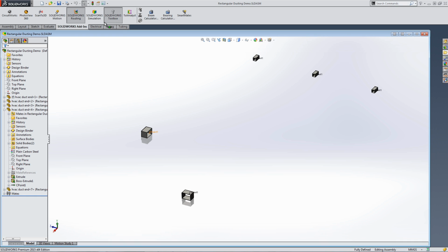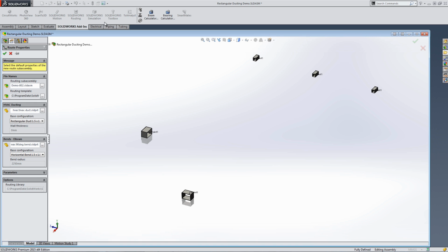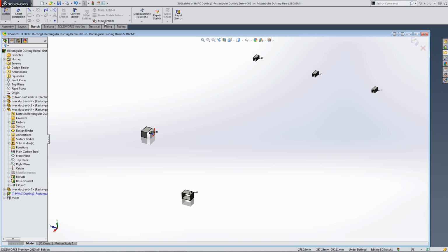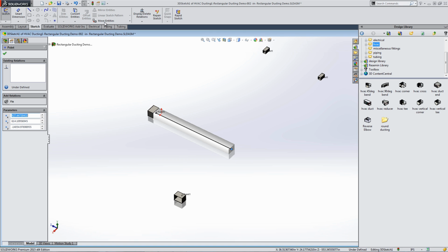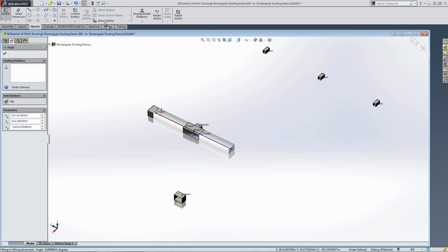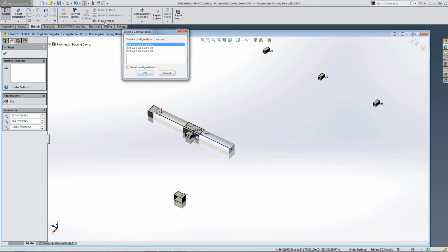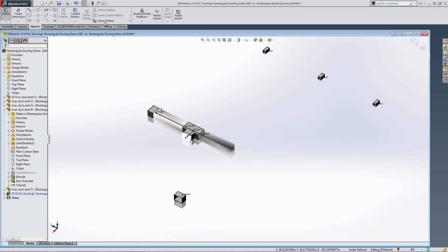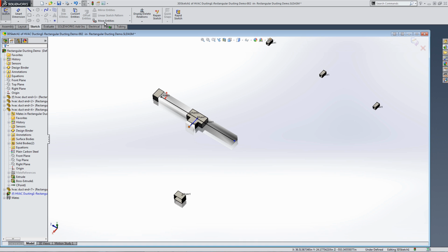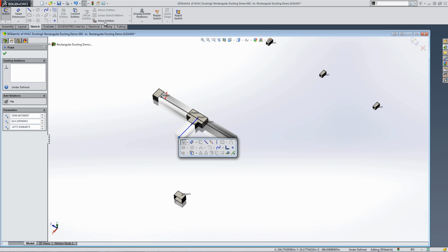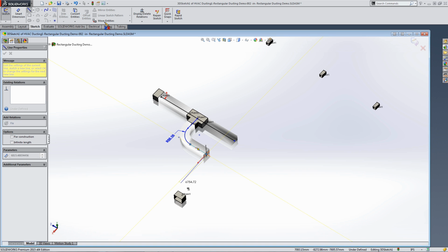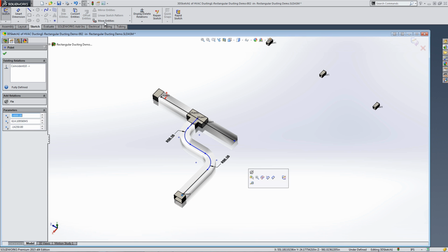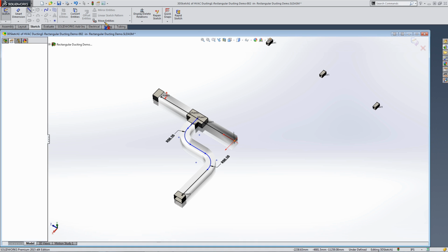So what I can do is start a route here, and what we're really looking at is a rectangular profile for HVAC. So now we support rectangular profiled parts too. So I could drag this part out and put a T on it, drop that on here, give it the same size, and let's pull this down a little bit. Maybe we have to jog around a column or something like that, so we're going to make an S-curve over here. Snap this right onto the other one. Looks good. Then we're going to come up here.